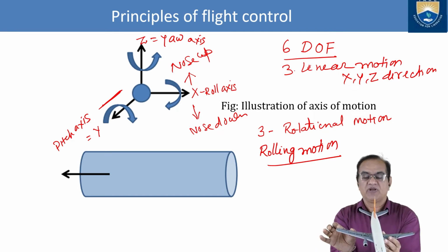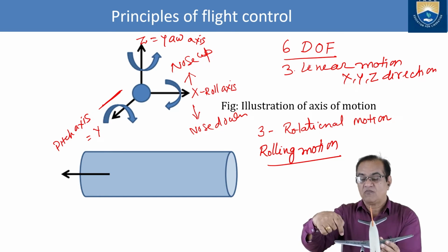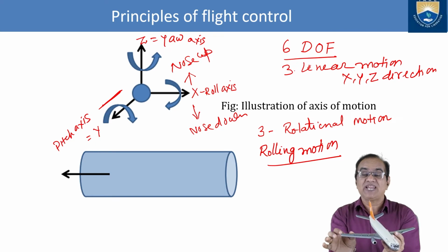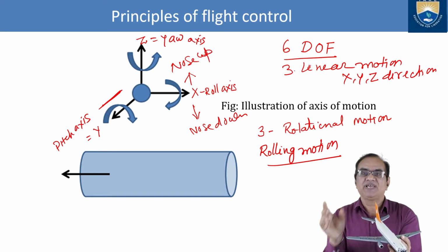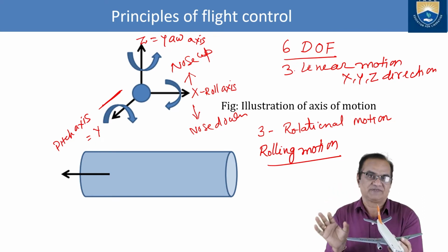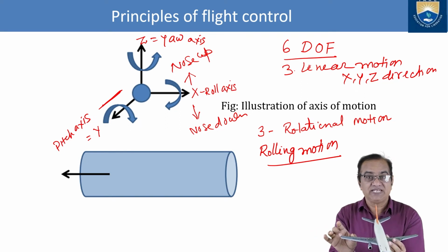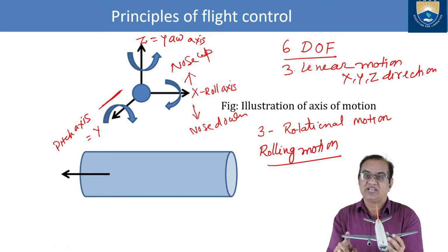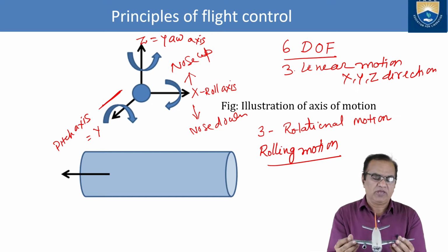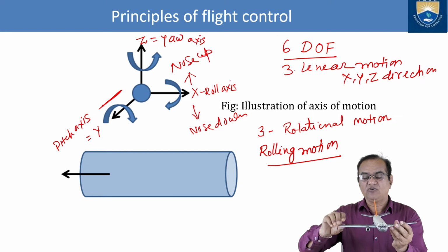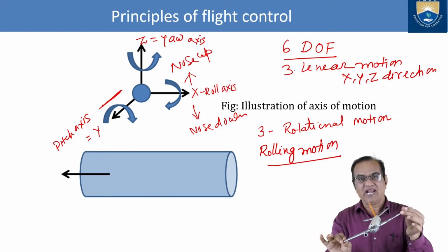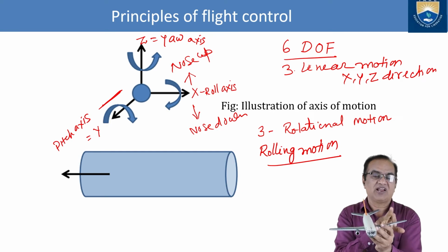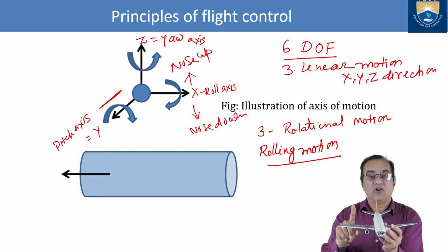Ailerons are at the tip because from here, force into distance, a maximum distance should be there so that we can use a small size of flaps or ailerons. So we need these ailerons far away from the center of gravity. Now if I want to make a roll with the right wing down, then I need to generate a high force or high lift in the left wing and low force in this.